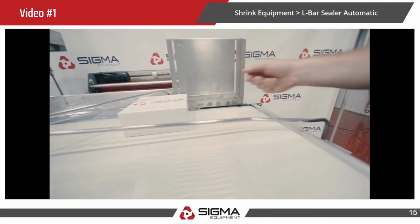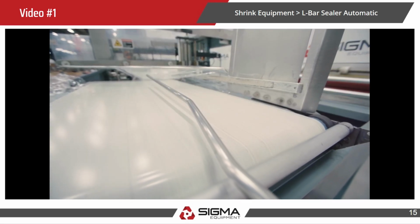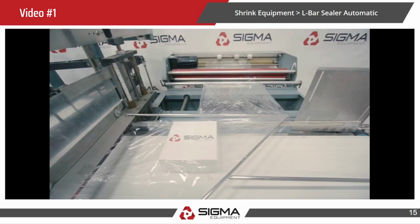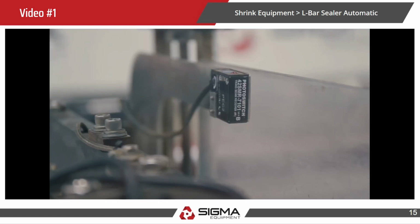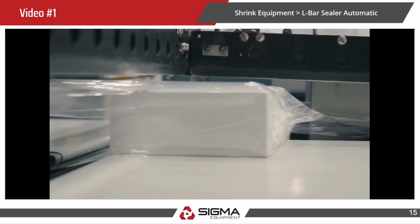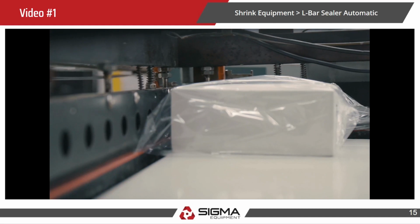First, product is placed on the in-feed conveyor. A product guide bar helps direct the product into the film tunnel. As the product moves off the in-feed conveyor, a photo eye sensor detects when the product is clear. Once the product is clear, the conveyors will stop and the out-feed closing conveyor will then retract.